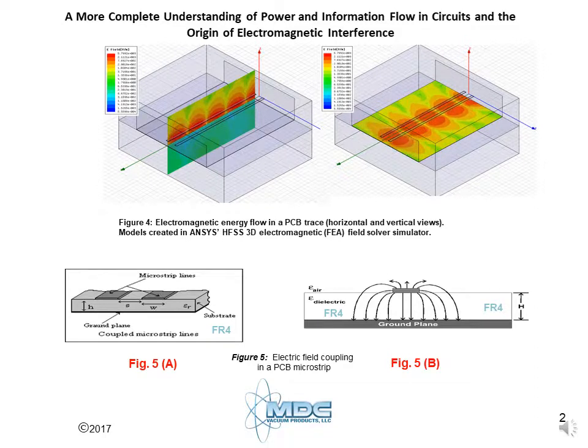On the bottom of the circuit board is another layer of copper known as the ground plane. Sandwiched between the copper traces and the copper ground plane is an insulating or dielectric material. FR4 is a commonly used material. Together, the top traces, the bottom ground plane, and the dielectric substrate form a transmission line. These are the minimum elements needed to transmit information, for example, digital signals, as well as power. That is, two conductors and a dielectric medium between them. Now, back to the animation at the top of the page.